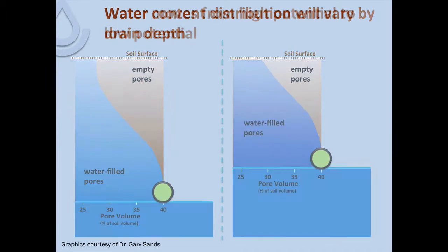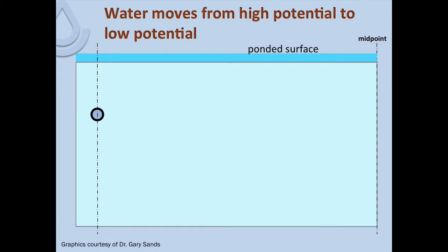Now, as we look at how drainage actually works in the soil and how that water moves through the soil to the drains, when that drain system is operating at its design capacity, we've always got a free water surface or a little bit of air all the way through the drain lines into the field. And so we've got zero or gauge pressure, or atmospheric pressure, within the pipe.